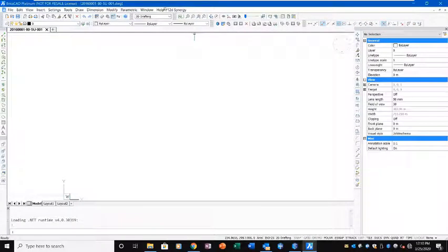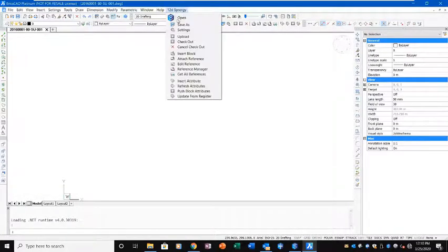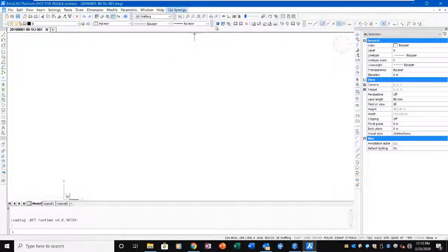All right, so yeah, you have your 12D Synergy menu. AutoCAD will have a ribbon, obviously, as well, and you will also have your 12D Synergy toolbar. One of the first things you're going to do is build up your drawing using Xrefs. So one of the biggest differences here is just when inserting a block or XREF, you just use the insert block or insert XREF commands from Synergy.